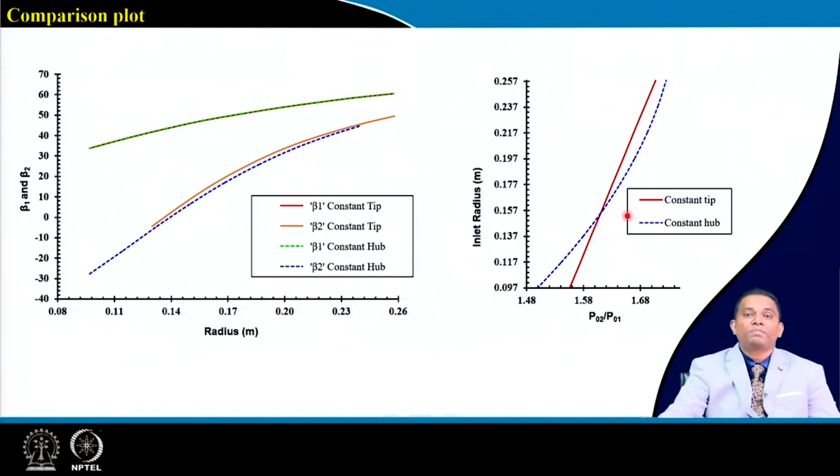And finally, as per our engine configuration, we need to be very careful. We are talking about design for a single stage at this instant, and we know our compressor for an aero engine, a land based power plant, or the process industry is made up of a number of stages. It's a multi-stage axial flow compressor, and for that you may need a number of design iterations, where your understanding and expertise will help reduce the number of iterations.